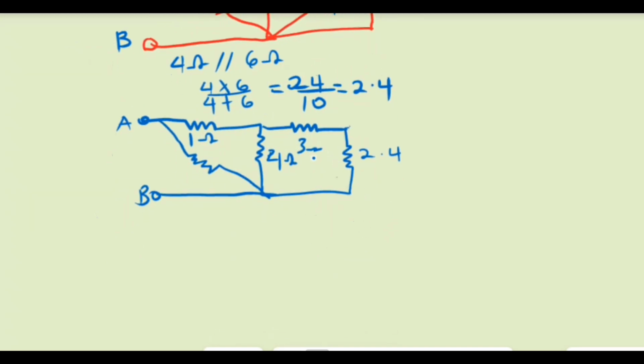So at this point, we have our 3 ohm here, we have 2.4 ohm, which is the farthest part of our loop. When you consider these two again, you realize that there is no node here between the two resistors, and hence the same current will pass through when it starts from here. So this is a whole branch in which there is no node in between the two resistors, or current will not split in between the two resistors, hence they are in series. So you find the series resistance of 3 ohm plus 2.4 ohm.